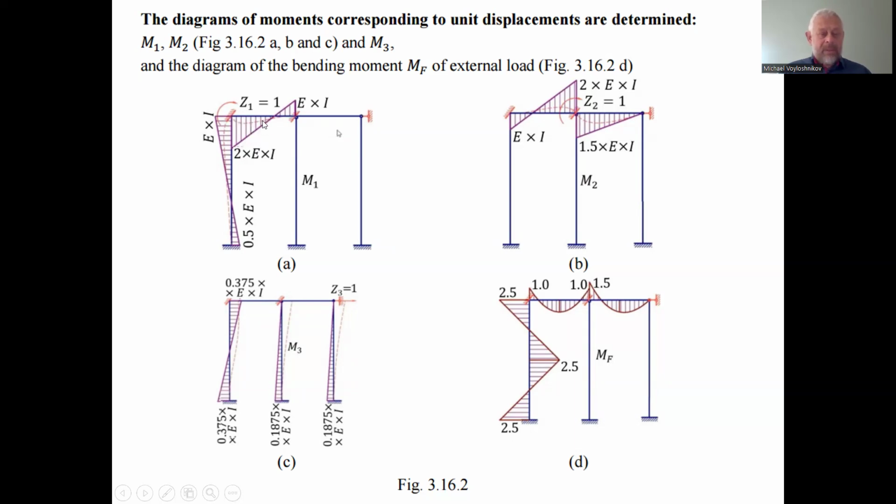So we have previously taken decisions, usually. In the textbooks of structural mechanics, in the chapter on the displacement method for the decision of statically indeterminate mechanical systems, or in the directories available online, we have a lot of tables containing the previously obtained decisions for single-span, two-supported mechanical rods.